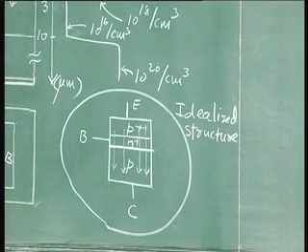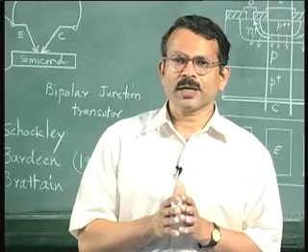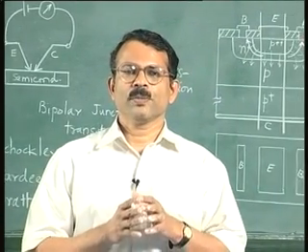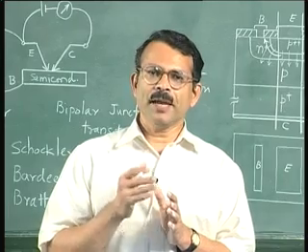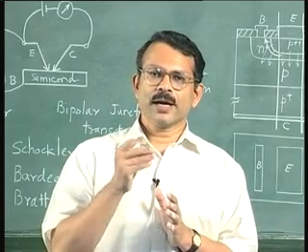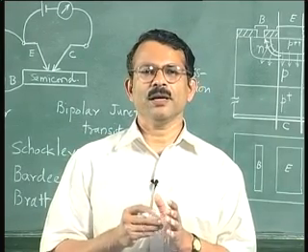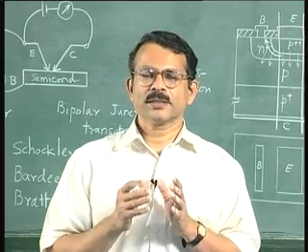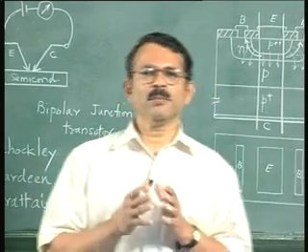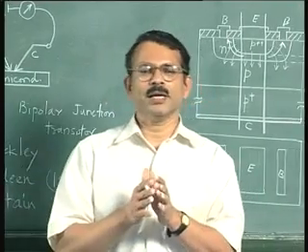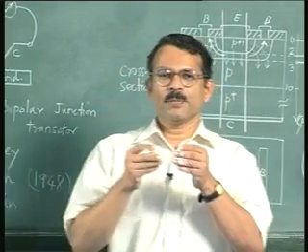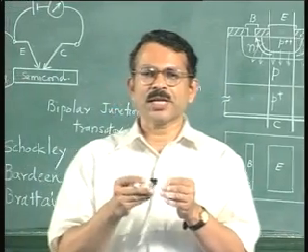Now, as we will see, in a bipolar junction transistor the current is because of diffusion. So if you consider a PNP transistor, the current direction will be the same as the direction of the hole diffusion. That is the reason why a certain simplification results, because the current direction is the same as the direction of the movement of holes. The understanding of the transistor action is simplified.